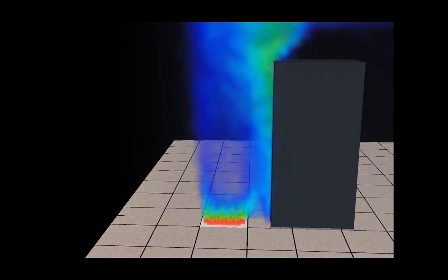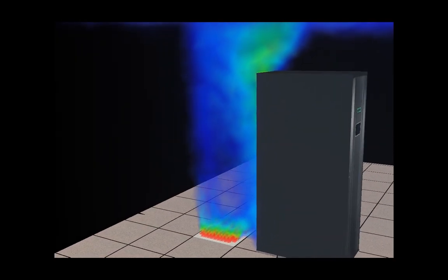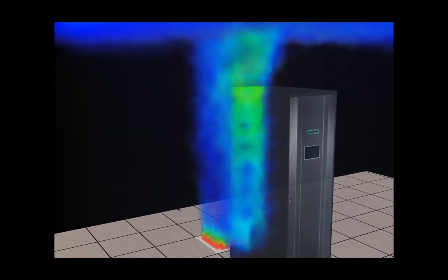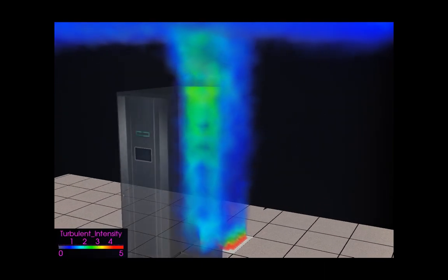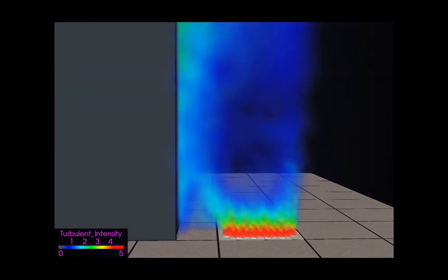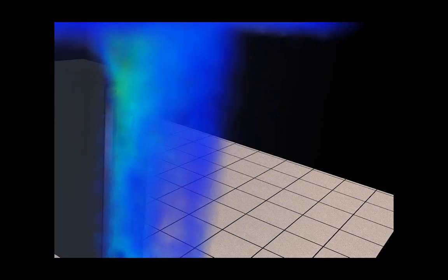The result is a more uniform temperature variation across the rack inlets, resulting in superior heat transfer through and away from the rack. You can see this effect in these CFD results shown here. The areas in red represent high levels of turbulence, and blue indicates low level of turbulence. It is easy to see even uniform distribution of cool air across the entire front of the IT rack.